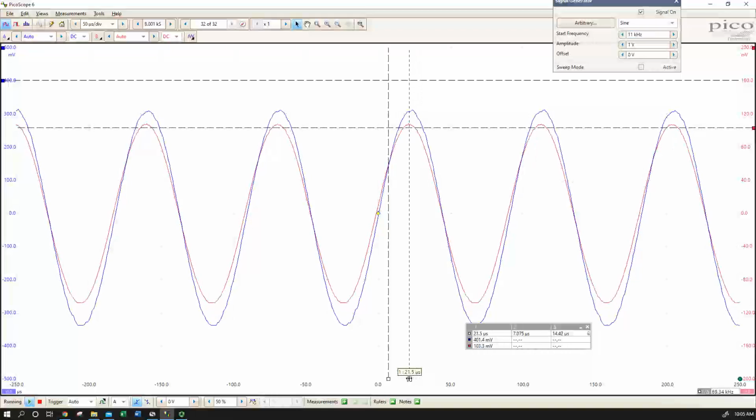But generally speaking, we can tell we're at resonance because our total circuit voltage drop and the voltage drop over a pure resistor are almost completely overlapping. They're completely in phase. That's because the impedance or reactance of our inductor and capacitor have completely canceled out. So no imaginary component here. So it's purely resistive circuit.